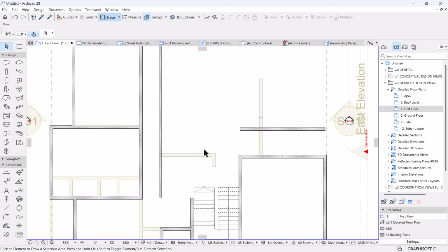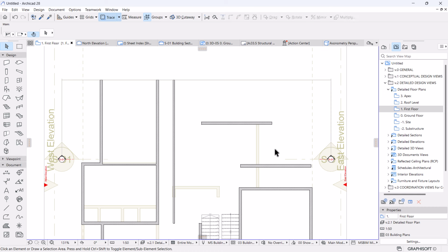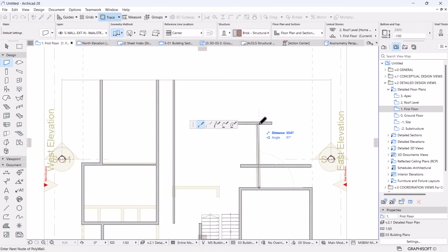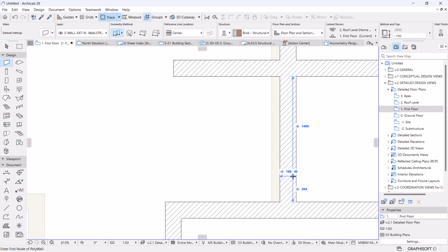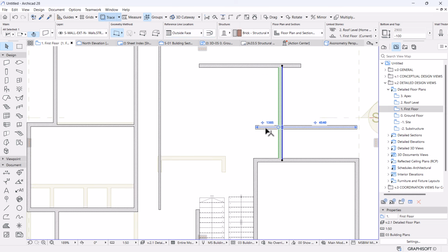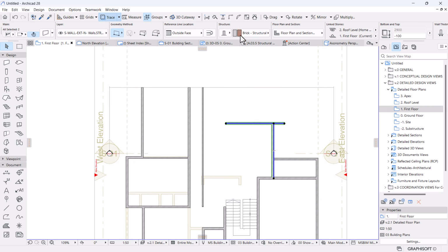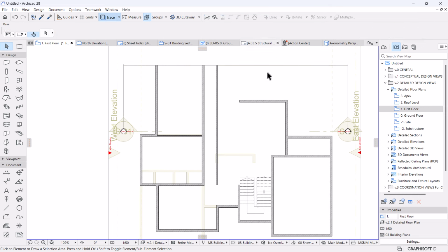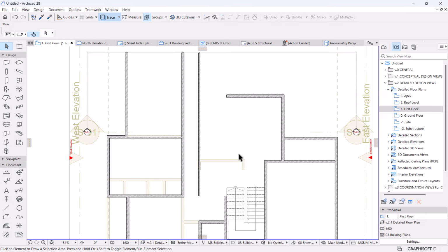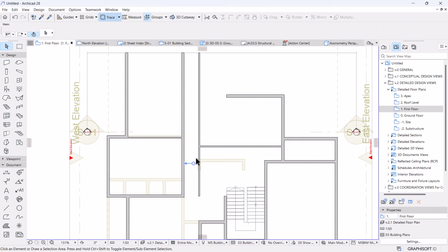Then this area will have a kitchen, so I'm going to copy this wall and put it there. So a kitchenette of 3.5, something like that. Pick parameters of this wall and place it there. Right click, hit OK. Make sure the position is right, then I can flip it that way. Yes, trim it off. This you can intersect to enclose our storeroom. Then also this can intersect. I kept on saying chamfer, but rather it's an intersect feature. Okay, so from here we'll have a wall that will now enclose our kitchenette.